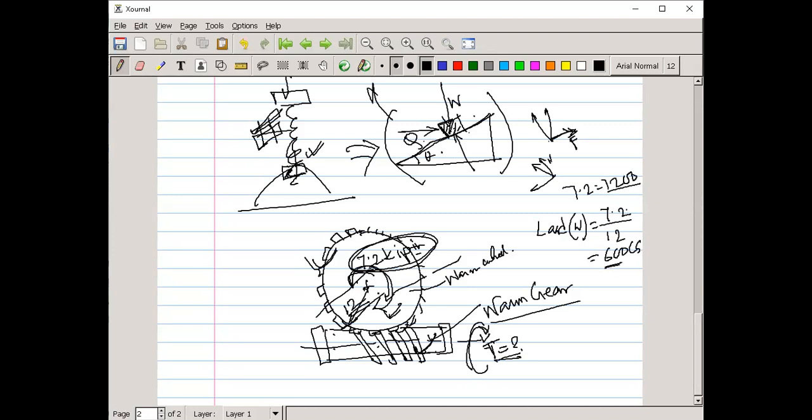So it means we have to apply such a torque so that the worm gear can rotate the worm wheel which has a 6000-pound load. Understandable? This worm wheel is connected with a load of 6000 pound, and we have to rotate it. So how much torque is needed to rotate this one? Is the question clear?